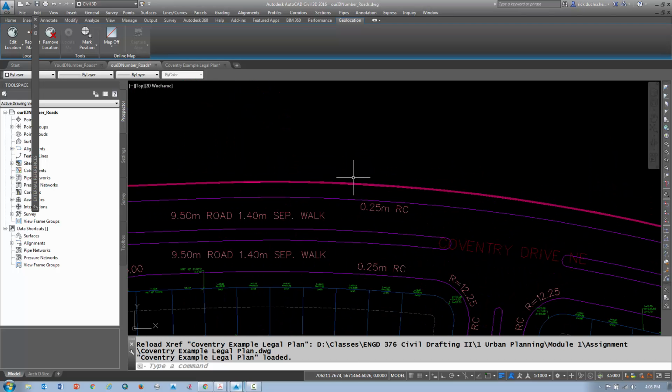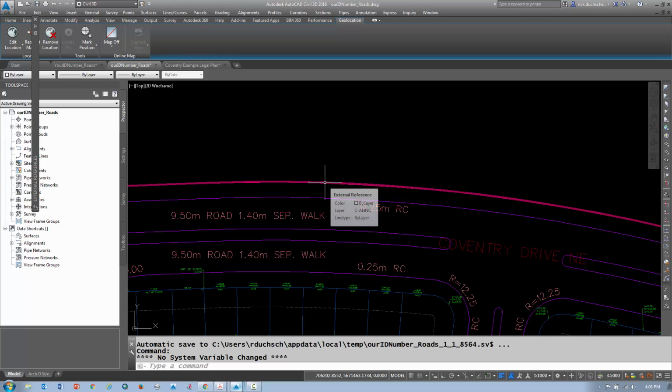So what you want to do is make sure you've got your line weight button turned on so that you can show those property lines a little clearer. But we've got some existing property lines here. These lines represent our gutter lines. These are our medians, and we have some more gutter lines on the other side of the street. So the property line runs from one side of the street over here to the other side of where your lots have been created.